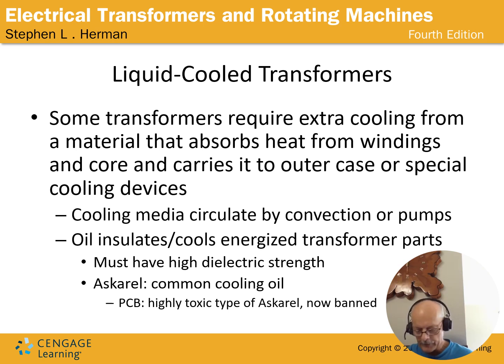If I'm thinking of the right thing, but I think I am. One of the reasons it has to be something like that is because it has to have a high dielectric strength. If this oil is easy to arc through, it will start letting arcs carry from the transformer to the shell of the transformer or to ground, and it will burn up the transformer and ruin it in short order. So it has to have a high dielectric strength.